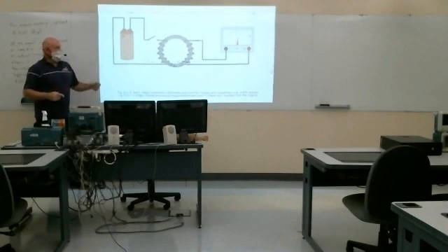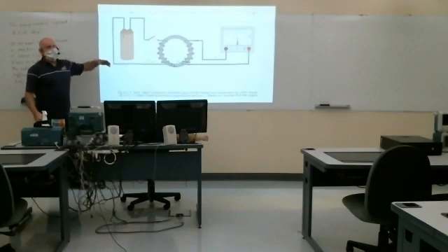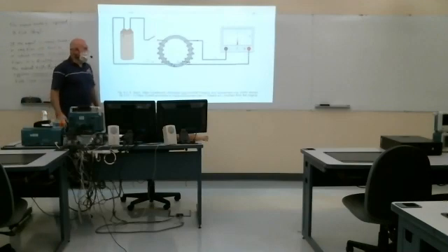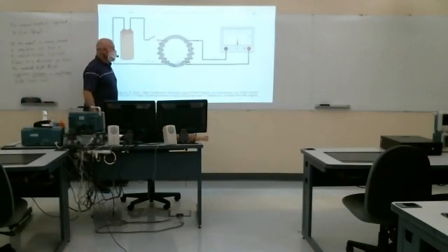So as I close the switch, I'll see the voltmeter swing to the right. And then it'll go back to 0. I open up the switch, I'll see my voltmeter needle swing to the left, indicating a negative voltage, a negative induced voltage, and then it'll go back to 0. And then I could just repeat that.